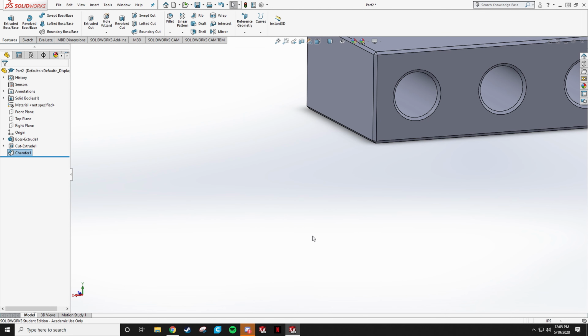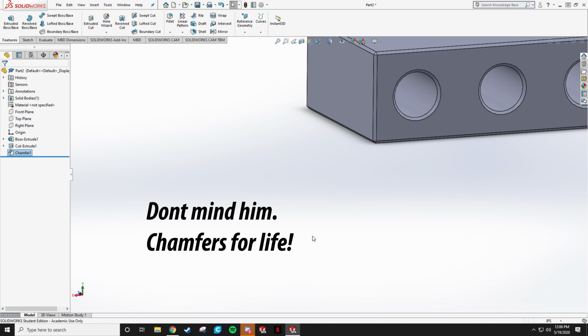Basically, a chamfer is just a cut. You can adjust the angle of the cut, whether it's 45 degrees, 80 degrees, what have you. A fillet is just a round over. There are deburring tools that you can actually use to fillet. I would highly suggest against that. They're mainly for deburring after machining, but they can be useful for taking off that edge to help a bearing slide in and stuff. But if you like chamfers, I'm not going to shame you.